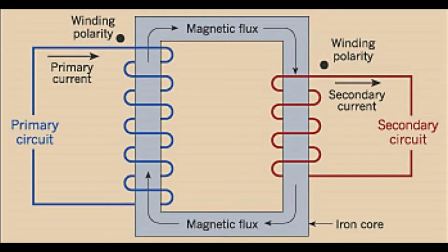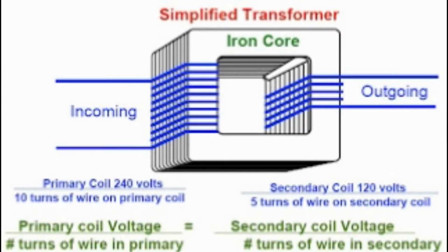There are four primary parts to the basic transformer. The parts include the input connection, the output connection, the windings or coils, and the core. Input connections. The input side of a transformer is called the primary side because the main electrical power to be changed is connected at this point. Output connections. The output side or secondary side of the transformer is where the electrical power is sent to the load. Depending on the requirement of the load, the incoming electric power is either increased or decreased.